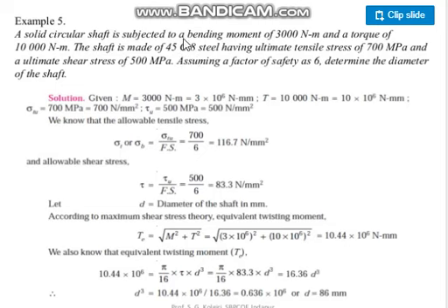45C8. Though the value is not given, the nomenclature of the steel is given. We are not going to use this anyway because we are not allowed to use data books in the exams. If data books are allowed, then they will not give the values, because we can see from the data books. Actually this is a carbon steel having 0.45% weight percent of carbon and 0.8% of manganese. That is the carbon steel.